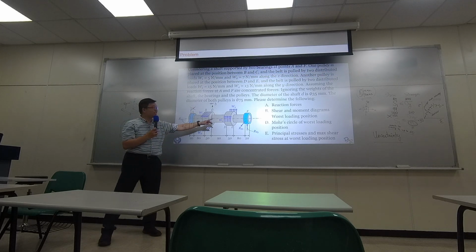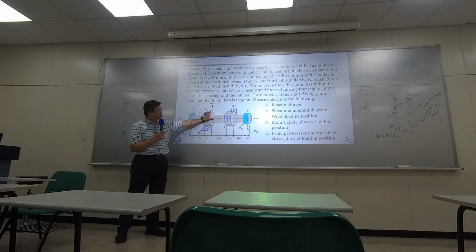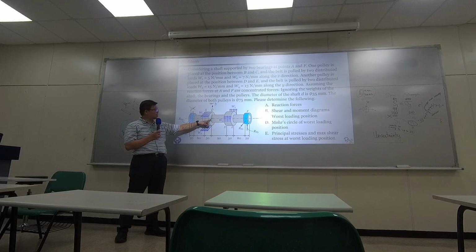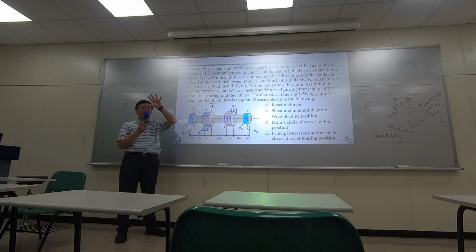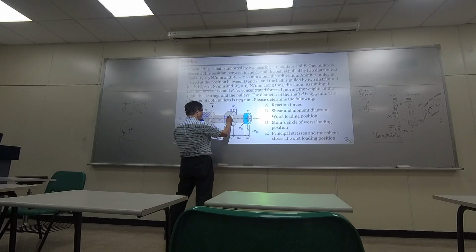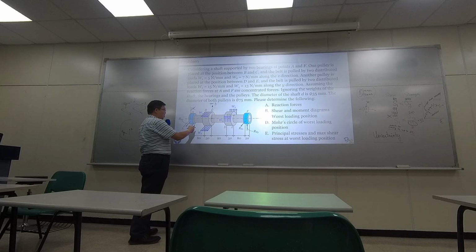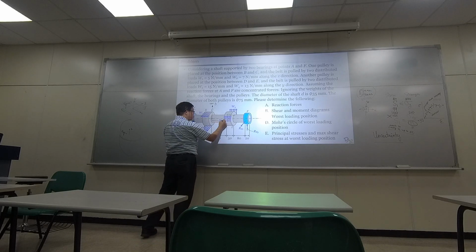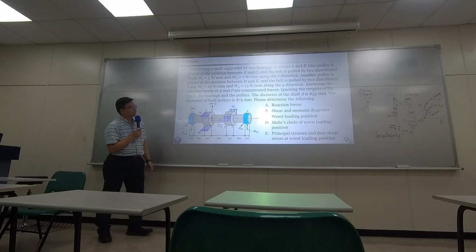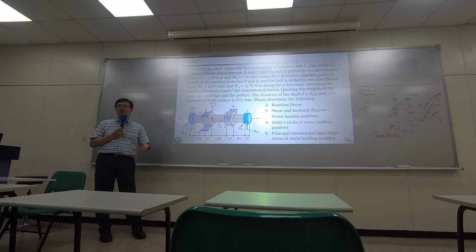Okay. If I change the coordinate y to a different position, everything changes. Because all the calculation will be based on this new coordinate. And you can follow exactly what has been introduced in the PowerPoint, but based on this new y coordinate. So you should get the exact same diagram and results, but because the coordinate is different, later on when you find the worst position, earlier it was 256 millimeter. In this new coordinate, the position will be different. So this will be a new position, new value right here, right? So just make the change of the coordinate by shifting here to here and do the exact homework.